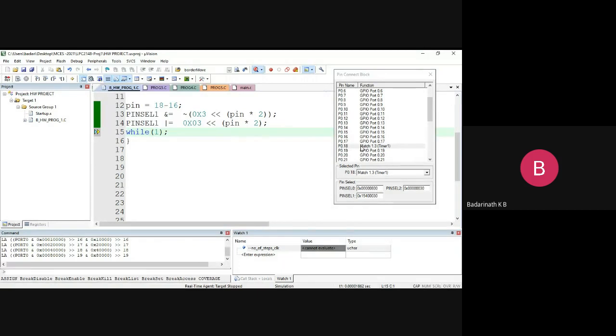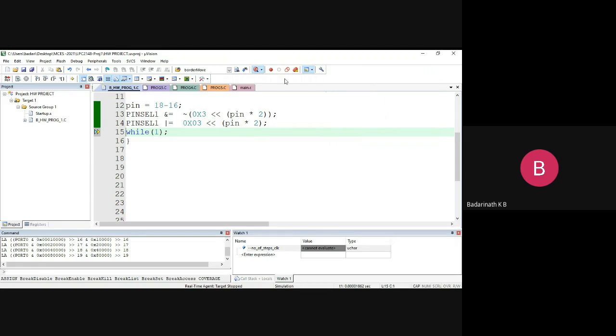So the same pin can act as what? The four different roles it can play, each pin. Now what is the role it's playing? The fourth role it's playing. So that means that this pin is being controlled by the timer hardware or the timer peripheral or the timer block present inside the microcontroller. So this completes understanding about the pin selection register for the microcontroller LPC2148.